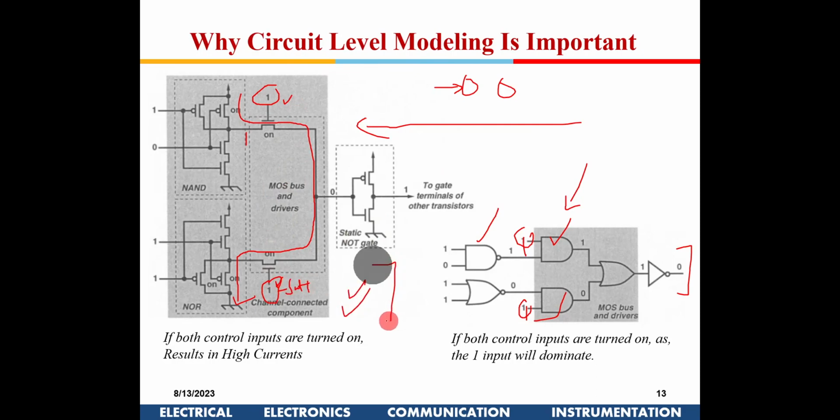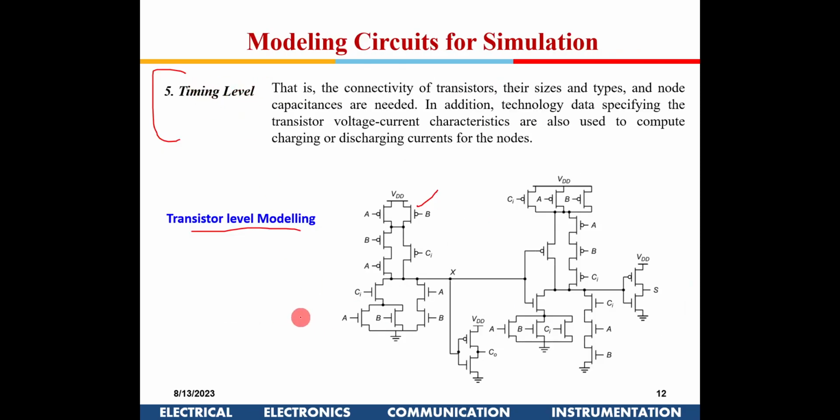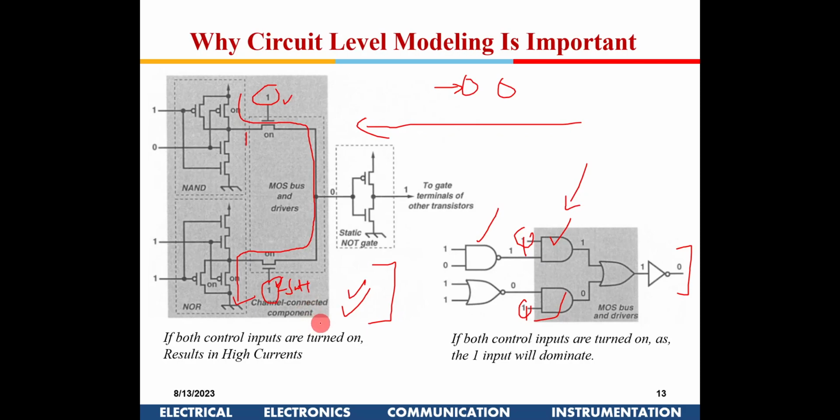It is a time consuming run, but this needs to be done at the last. Because after doing the transistor level, you will do a layout, and all those parasitic delays also will get incorporated. So that final run at the transistor level is also important. Okay, so does that answer your query? Why do we have these different kinds of levels of testing? It is time versus accuracy.